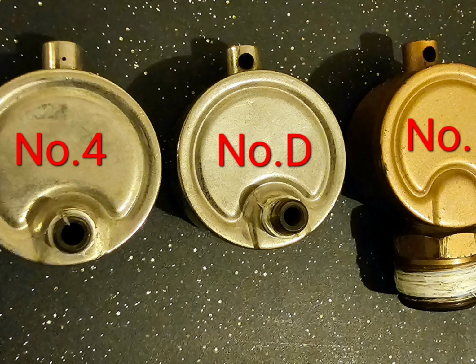And then at some point, if the system is running for a long period of time, it's going to start to pressurize. And when she pressurizes, that thermostatic element on the inside of the body of the vent is going to be forced into the closed position. So as long as there's pressure on that system, guess what? This thing will never drop back down. That's where you need to drop away pressure for this particular air vent, for this particular application.